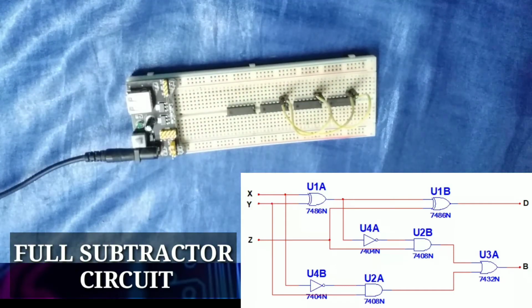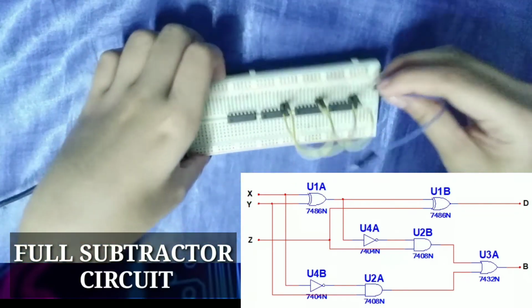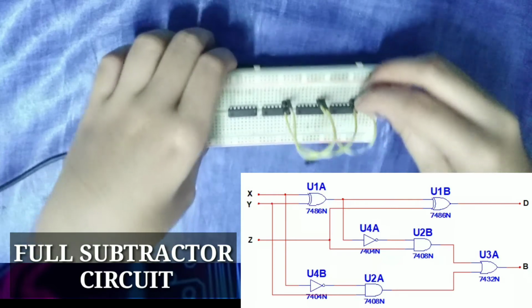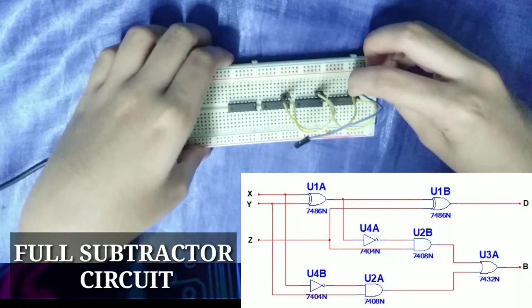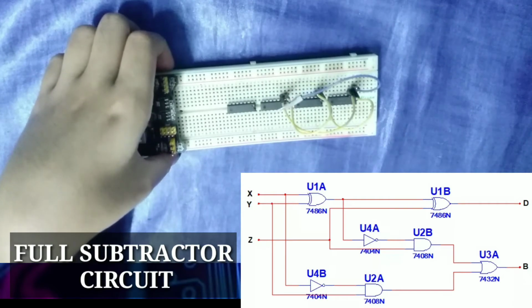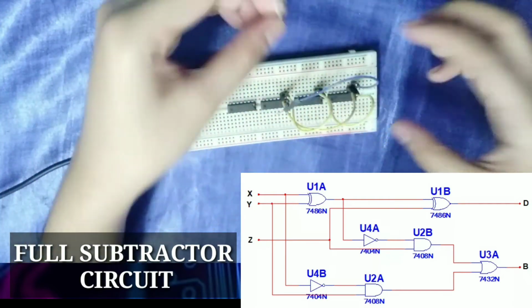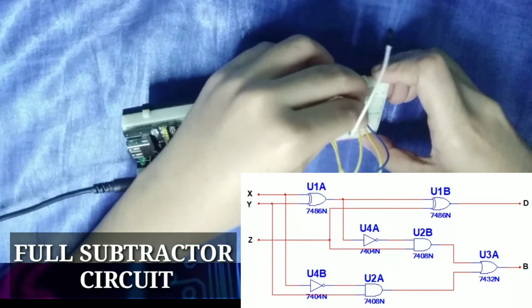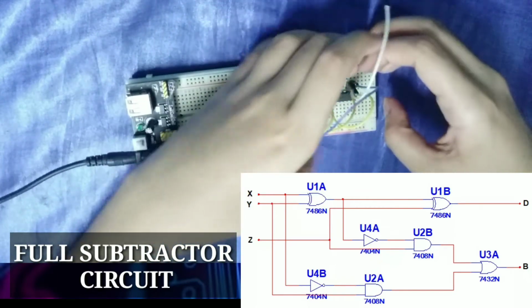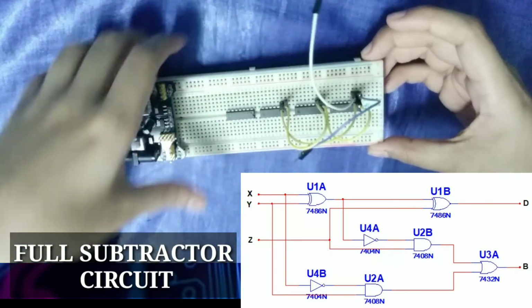Now, as our input, let's consider the blue wire as our input X, which will be connected to pin number 1 of the 7486. And let's consider another colored wire, our white wire, as our input Y, connected to the second pin of our 7486, as you can see here.